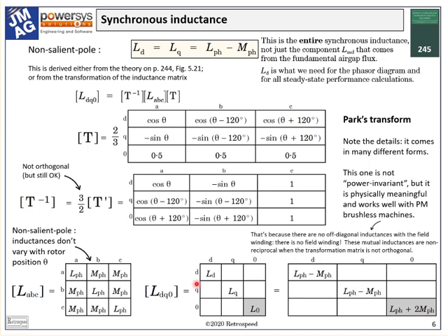There is, of course, a corresponding transform for voltages, flux linkages, and currents, using only the T matrix with a vector of currents or flux linkages or voltages. But it turns out that if the machine has a star-connected winding, the 0 component of current is 0. So this element in the matrix becomes redundant.